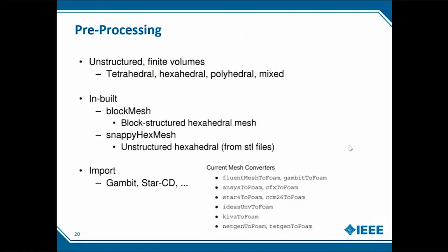So yeah, now about pre-processing. OpenFOAM is based on finite volumes, and you can have any mesh. You can have an unstructured or a structured mesh. It can be tetrahedral, hexahedral, or mixed, or anything. And two of the main commands used to build your mesh, that is to mesh the domain that you have, are known as blockMesh and snappyHexMesh. Now these commands are case sensitive, so you must type the M capital. You cannot really type it small.